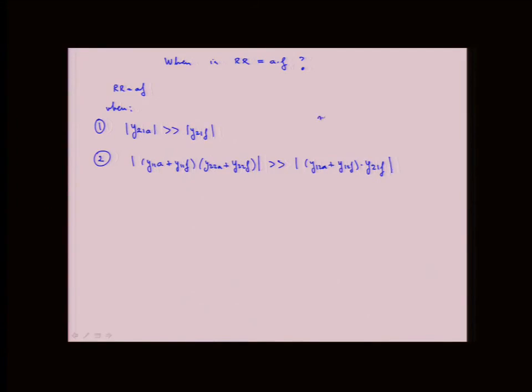See here, read G, H, and Z, and we're also assuming that YS and YL are lumped into Y11A, Y22A. In other words, the loads are absorbed into the amplifier admittances.